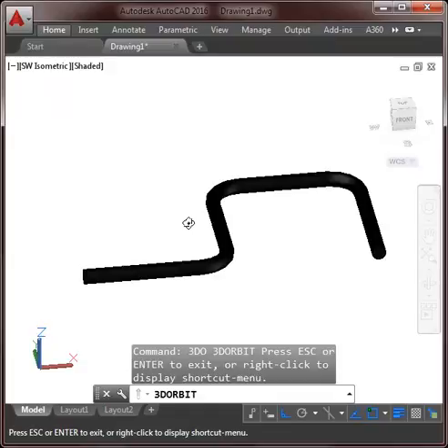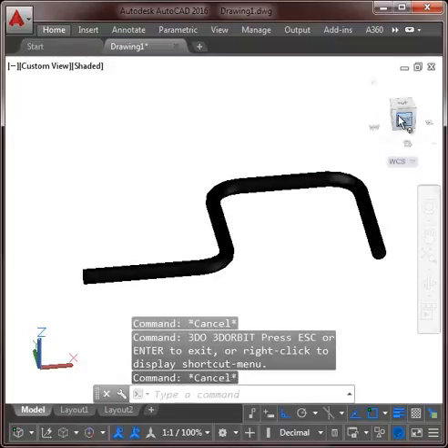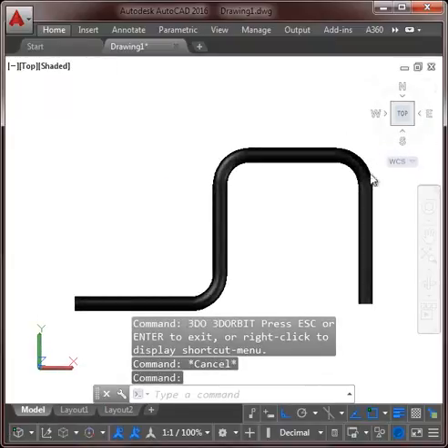You just get your object to be extruded aligned, and then you select your object, select your path, and away it goes. And where you might run into problems is if your circle is, in this example, much too large, then it might not have enough space to go around the corners, and it might get an error in that area. So that's one thing to look for. So I'm just going to go back to my top view again.